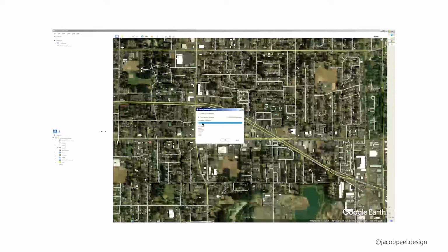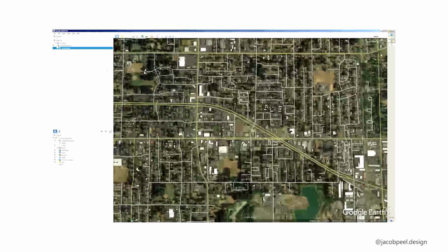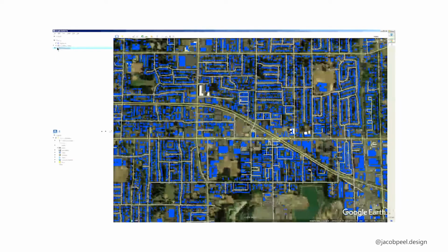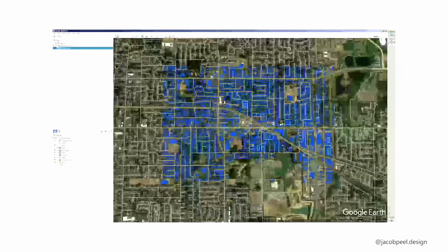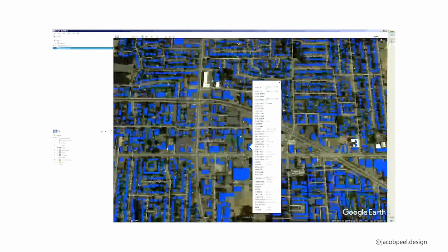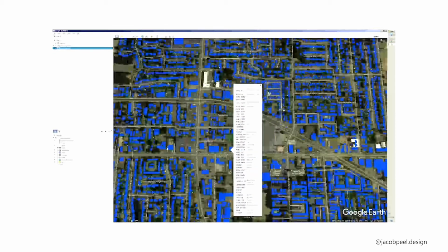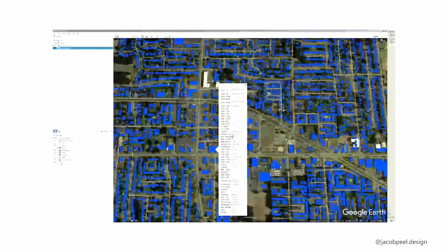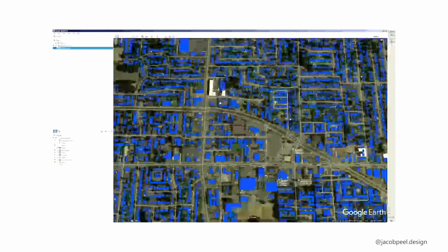So when we make this layer visible, we see a bunch of buildings, and it's cropped more or less to our view. We can see that these footprints, these polygons, have information associated. Average height, which will be nice. We'll extrude these footprints based on that.